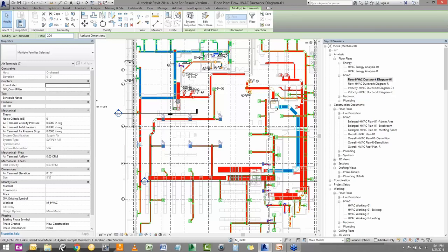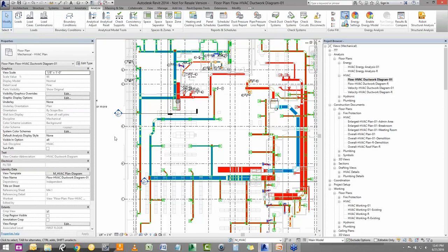Now after I hit enter, that flow rate's been applied and you'll see the duct automatically update to show that there's a flow. Now as with piping and ductwork and anything else inside of Revit, in order for flow to work, it needs to see a destination and a source. Since we just finally gave it a destination for the CFM, that's when this color legend actually autofills.